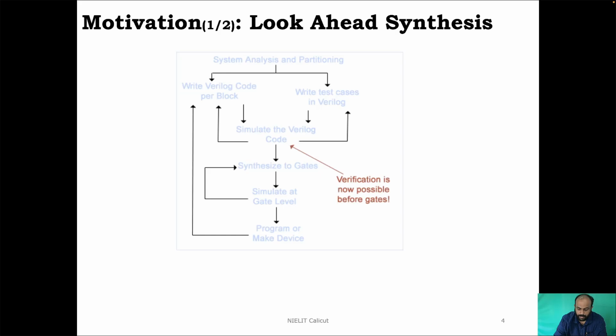seamless if you are using a hardware description language compared to schematic entry. So we can write the description as a Verilog code. We can give it for functional simulation, where the code which we have written, or the description of a hardware which we have written, will be subjected to different test cases that will expose the correct functioning of the design as per the specification.